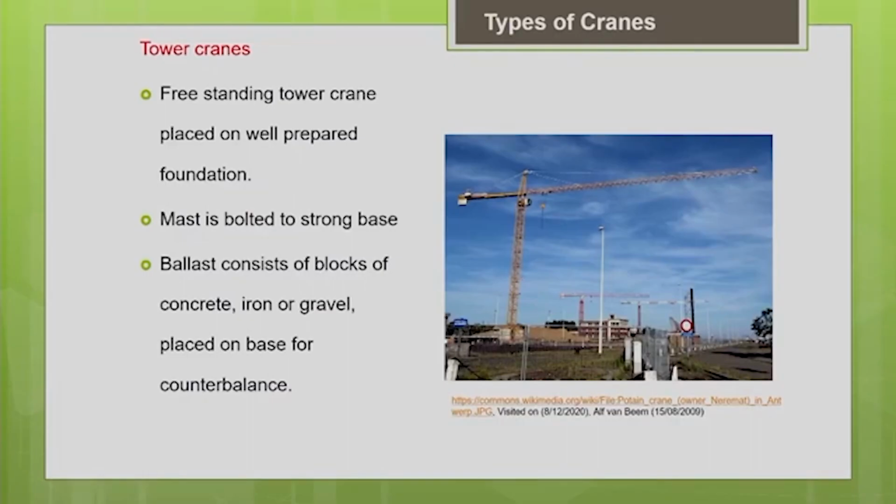Another important thing to be noted is that all these tower cranes should have a proper foundation. You should design its foundation very carefully with heavy reinforcement so that the load can be transferred through the tower to the foundation. You should go for a heavy foundation, and the tower sections will be bolted on with collars and extended bolts to the foundation.